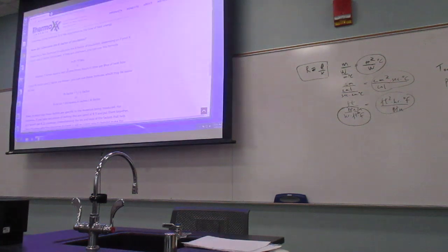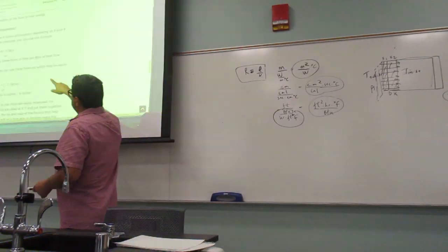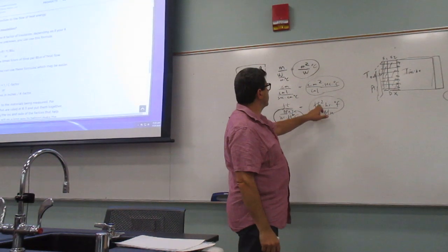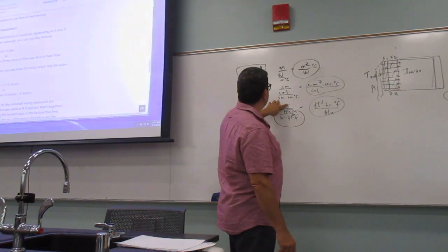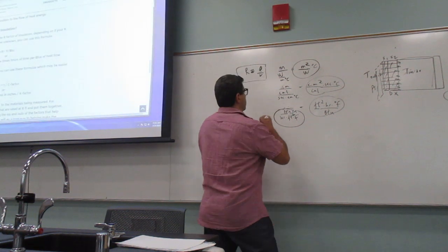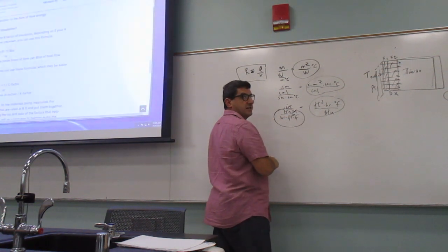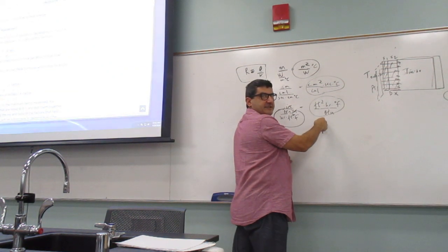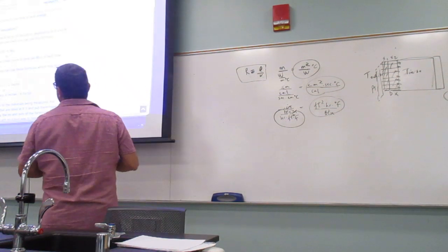Hour, feet squared, Fahrenheit over BTU. Well, that's exactly what I did, right? Hour, feet squared, Fahrenheit over BTU. So what they did is probably to say R is equal to inches over BTU, inches, hour, feet squared. The inches canceled, and then this one went up and became this. You see how they ended up with the same R factor units that we have. Okay.